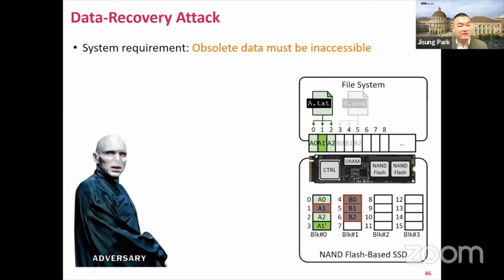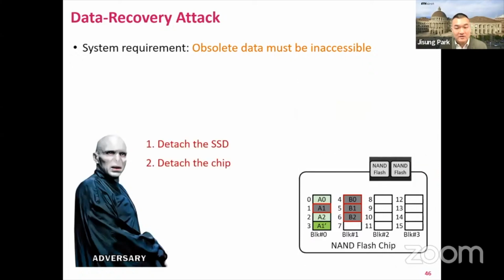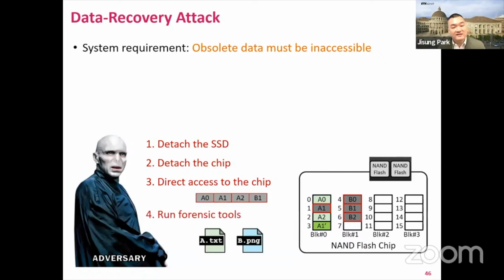However, if an adversary can detach the SSD from the system and desolder the chips from the SSD, then the adversary can directly access the chips with a custom flash controller to get all the invalid data remaining in the chips.